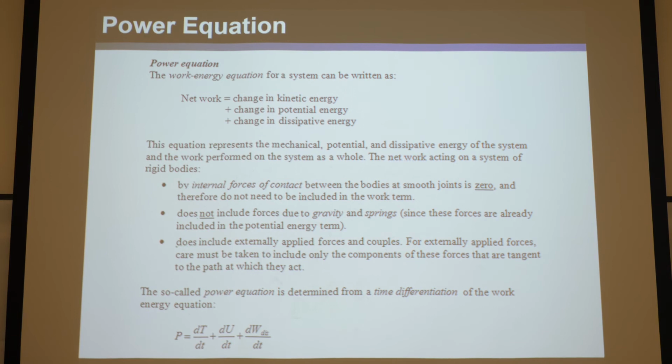Remember where you take F dot dr, that will make sure you consider the force component along the path, because that's what you use. That's what this is saying. But if you use that dot product, you'll always be fine. Okay, and again, you'd only need to worry about the dot product with the moments if it was a 3D scenario, but for planar ones, you don't need to worry about it, right? But you may need to worry about the sign for planar scenarios with moments. But you don't need a dot product.